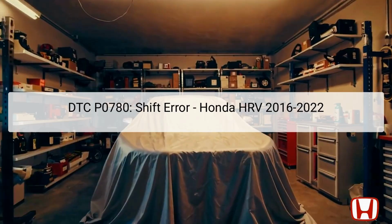The diagnostic trouble code DTC P0780 refers to a shift error, which is specifically associated with the continuously variable transmission (CVT) of the Honda HRV models from 2016 to 2022. This code indicates issues related to the shift control system within the vehicle's transmission.